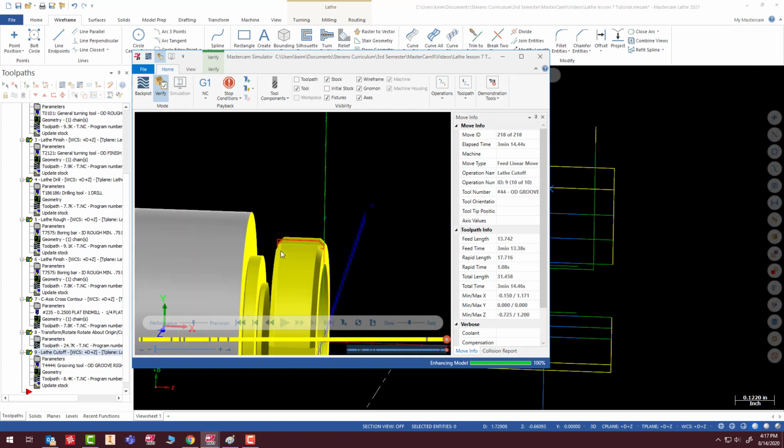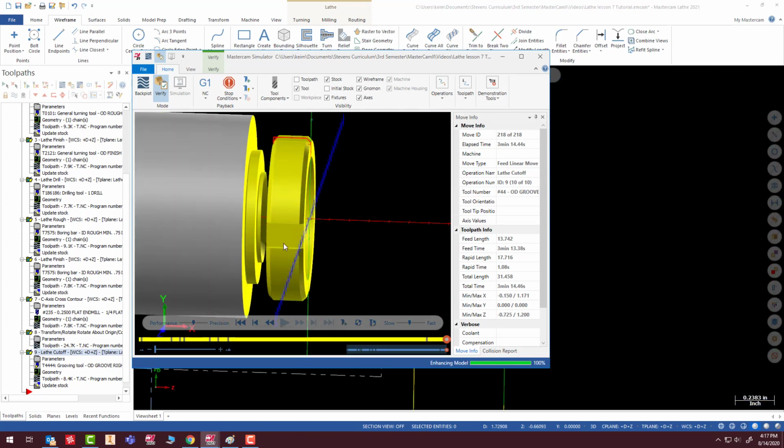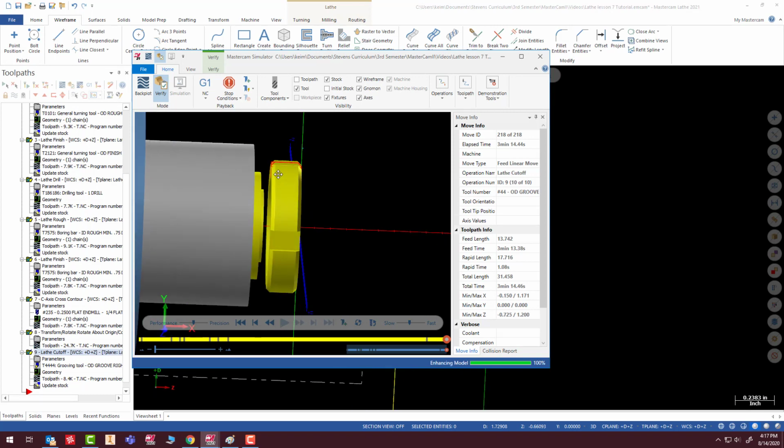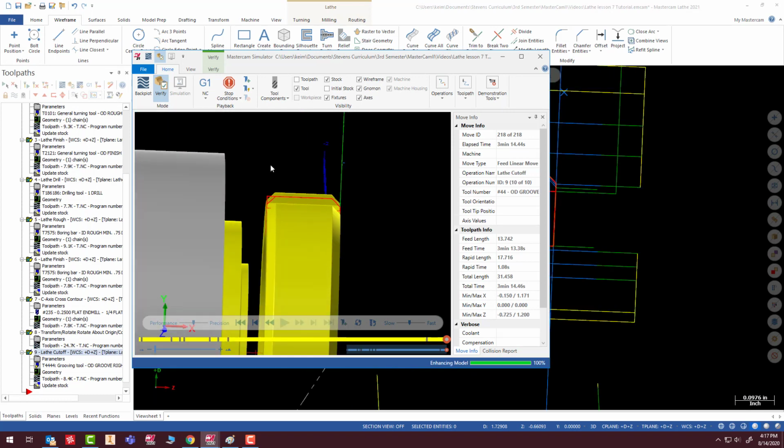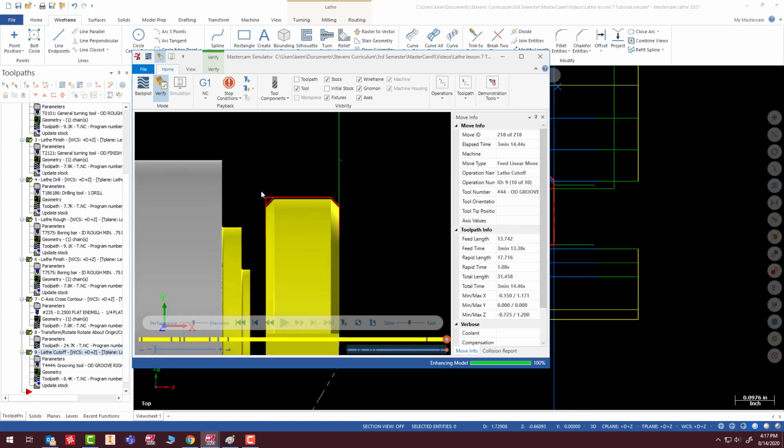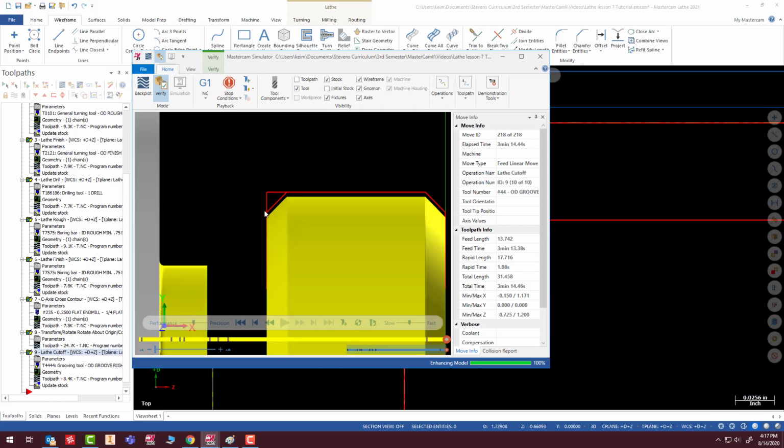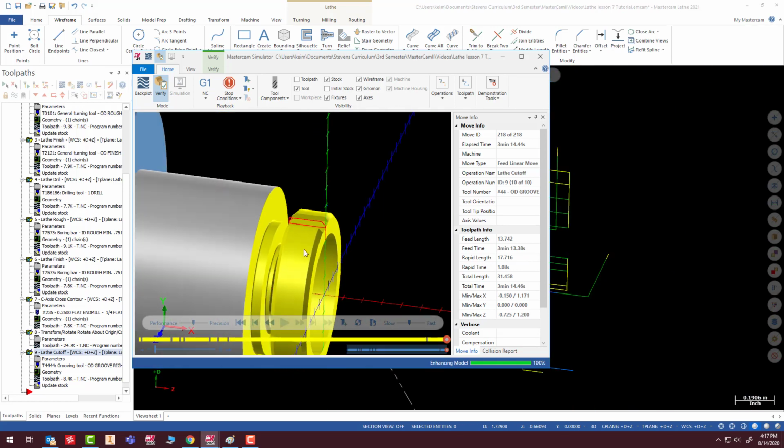So there we go. So the other thing this does, since this clearance cuts it, you actually can change your roughing. So your roughing only comes just past the part now, because it comes in and plunges this out, gives you enough clearance to make this cut without plunging on a diagonal. But that is generally the way I do these things.